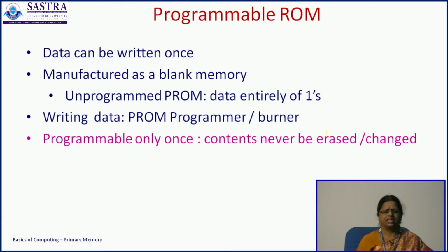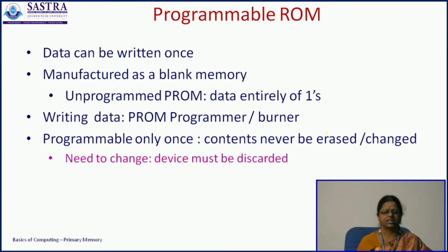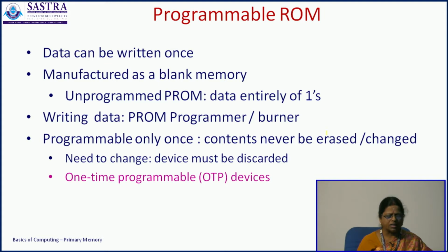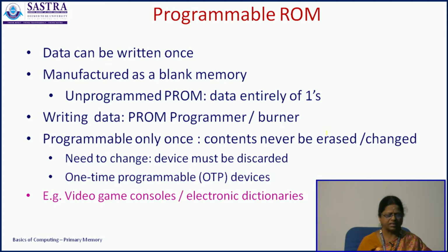As the name says, it can be programmed, but only once. The contents can never be erased or changed afterwards. So if we want to change any data, the device must be discarded. These devices are called one-time programmable or OTP devices. These kinds of PROMs are used in video game consoles or in electronic dictionaries.